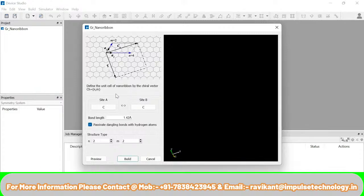A new window has opened where I can define the type of element that I want to use for the design here. I can define the bond length of my passivations of dangling bonds. I can activate this checkbox and define the chiral vector as per your requirement. Let's suppose I take the default one and click on the preview button.